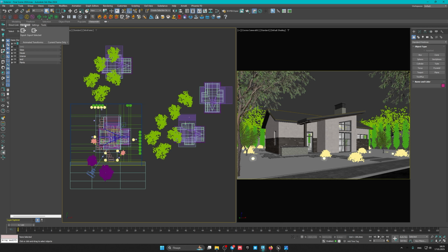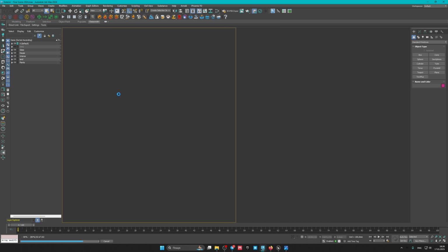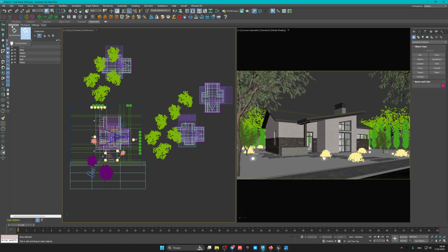The first option is just geometry being transferred to Unreal. We import it there, and further work is done only there. In the case of choosing Direct Link, we can continue working in 3D Max, and all our changes will automatically be transferred to Unreal. Let's try this. We try Direct Link, enabling auto synchronization. We see that Direct Link has started.